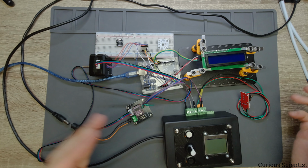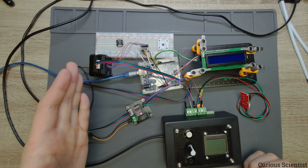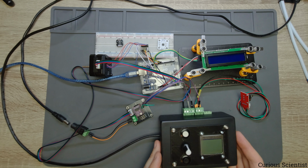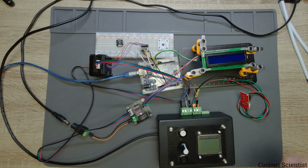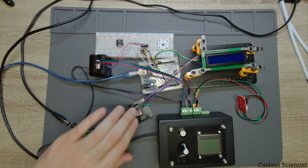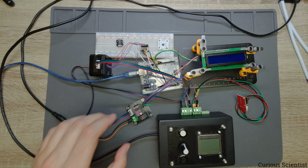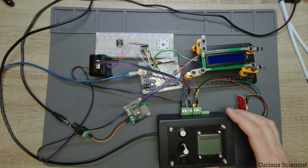For example, if you are using a linear actuator, you can put one limit switch at the beginning and one at the end of the linear rail, and then you can program it to act when the carriage hits the limit switch. And then we have a DRV8825 stepper motor driver on a breakout board, and that's all.